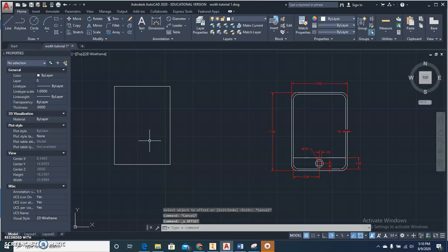So, I'll show you this one more time. O enter. It says type in distance, 0.15. A lot of times what happens is kids will click on the screen and you'll get some weird measurement because it wants to do whatever thing you just did. Okay? Don't do that. Type in O enter. Type in your distance, 0.15. Enter. No more, no less. No clicky unless I tell you to click.